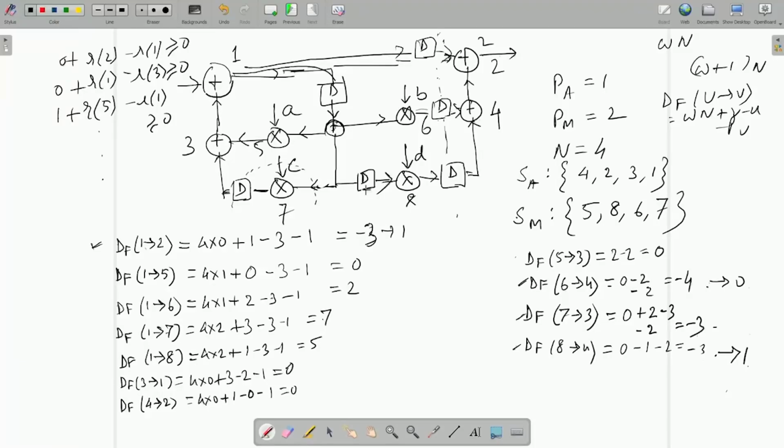This is the circuit we considered the other day, but the only thing you should check is this: in the forward path pipelining there was no problem, I brought in extra delay, but in the loop, wherever I moved a delay, earlier there was a delay here, here I moved it here. So, in this movement, some delay which was already existing in one of the edges has moved to some other edge. So, maybe one of the edges is now getting less delay; you can remove this dummy node now.